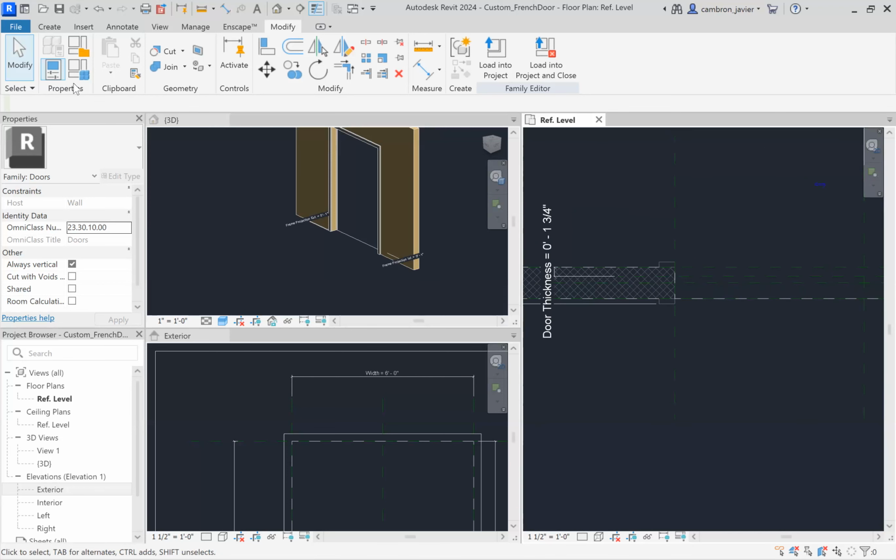Now, again, we're going to flex everything before we actually start to model. I know it might sound annoying, and it's a nuisance, but I guarantee you it's going to save you a lot of time. If we don't flex at every important moment, then if something goes south, it's going to be harder to figure out how far back we need to go and what the issue is. But if we're flexing at every single moment, we know the last thing that I did is what's wrong. So let me go ahead and take a look at that.